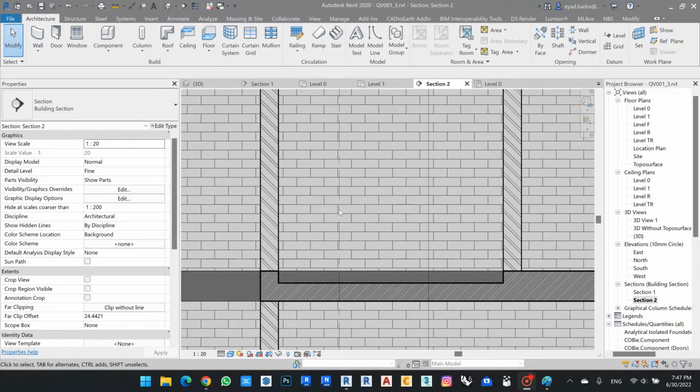As a small explanation of the layers of the flooring before we work in Revit, let me give an example of my flooring layers here. The first layer I need is a mortar, and the use of this mortar is to make the slope that protects my bathroom from the water. So the mortar will be like this, a rectangle with a thickness of 1 centimeter.